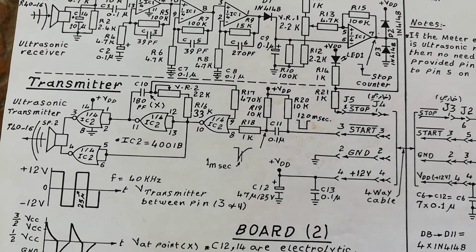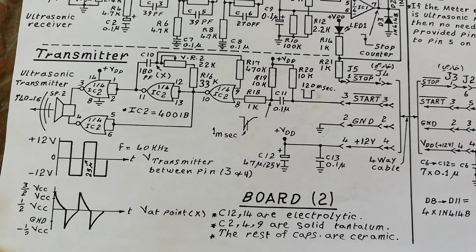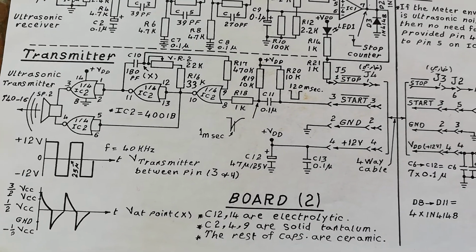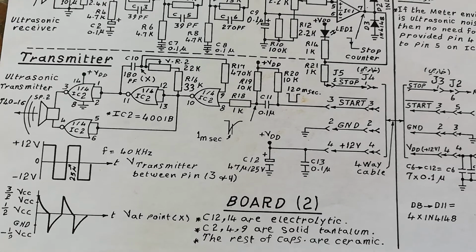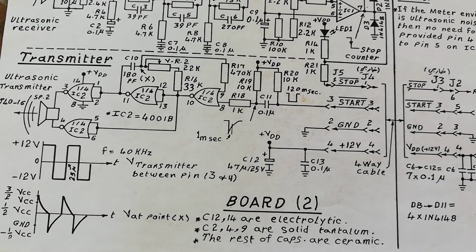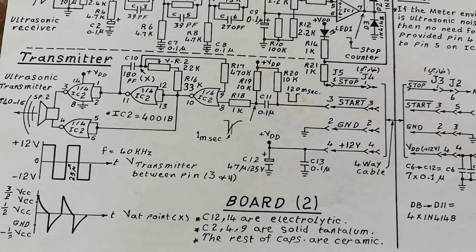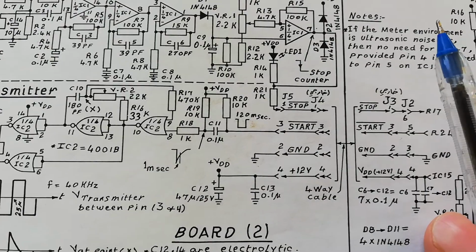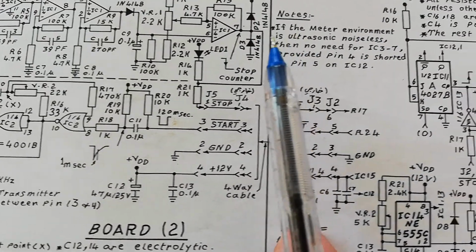And the transmitter is also down here. You can freeze the video whenever you want if you need additional information. And the transmitter is here. As you see, this works at 4 kilohertz for the transmitter. You send a burst of sound and you wait for the echo. And to verify, the reading usually should be done twice at least to make sure that the signal was right.